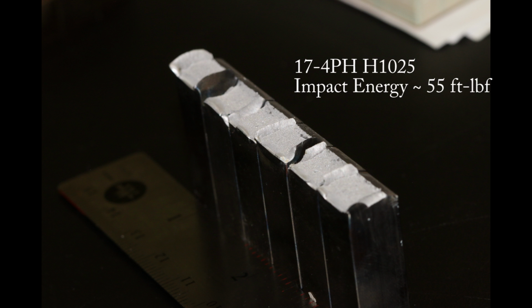So the impact energy for 17-4 PH in the H1025 condition was measured to be about 55 foot-pounds in this case. And that's about twice the energy absorbed, or more than twice the energy absorbed, as the H900 condition. But you'll notice that our strength didn't drop by half. It dropped by 20% maybe. So we didn't give up a whole ton of strength, but we gained quite a bit of toughness.